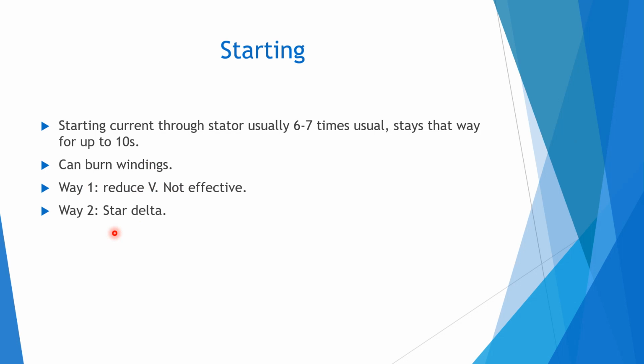Well, the stator has three-phase windings, right? So it has three different windings, and hence each winding has two terminals. We have six terminals. Now this can be looked upon as a balanced load, and you know that in a three-phase circuit, the load can be connected as a star or a delta. Now, why is this beneficial? So usually the motor is run as delta. It is connected as delta. Why? Because it has more voltage, it has more torque.